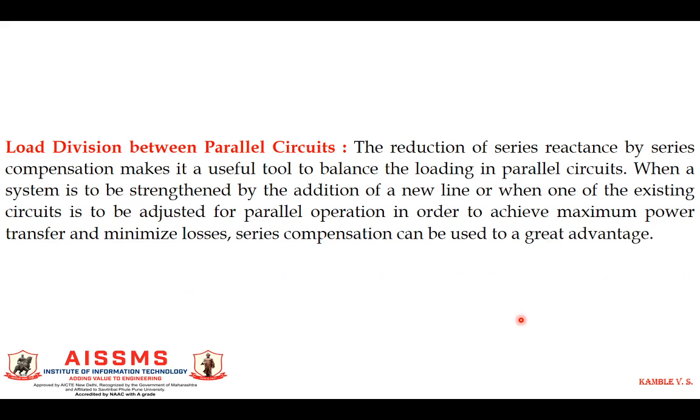Another advantage of series compensation is load division between parallel circuits. How is the load divided in the parallel circuits with the help of series compensation? The reduction in the series reactance by series compensation makes it a useful tool to balance the loading of the parallel circuits. When a system is to be strengthened by the addition of a new line, or when one of the existing circuits is to be adjusted for parallel operation in order to achieve maximum power transfer and minimize loss, series compensation can be used to great advantage.